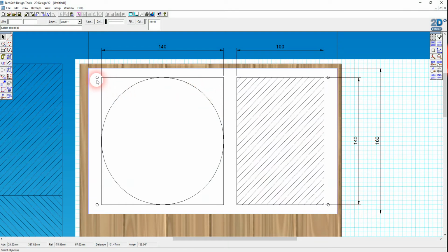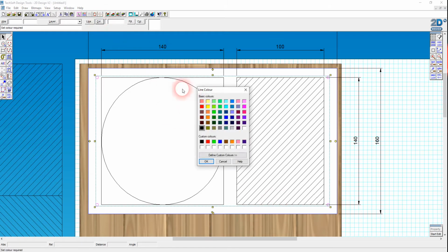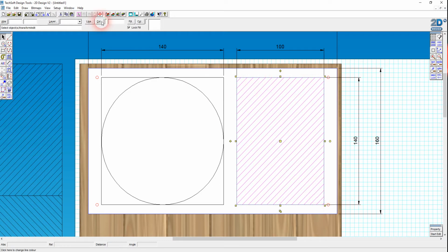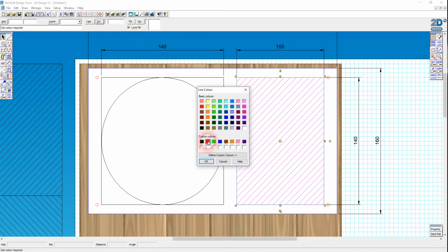And then I'm going to make it so that these 4 M3 holes, 3mm diameter holes, I selected and shift selected the other 3, are going to be just engraved. So let's make those red. In fact, I'll make it the red here from these custom colors. So these are our default colors for laser engraving and cutting. Okay, and I also want to make sure that this photo frame is going to be engraved as well. So let's just come to line color red.